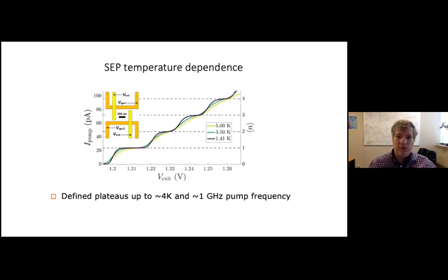And then just briefly mention, we can observe well-defined plateaus up to around 4 Kelvin and close to 1 gigahertz pumping frequency. So this is just to say that we don't actually need a dilution refrigerator to see quantized charge pumping. We can actually see it at a few Kelvin.